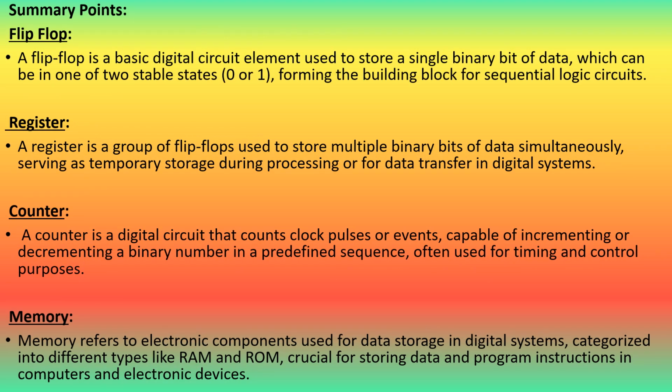Summary points. Flip-flop. A flip-flop is a basic digital circuit element used to store a single binary bit of data, which can be in one of two stable states, 0 or 1, forming the building block for sequential logic circuits. Register. A register is a group of flip-flops used to store multiple binary bits of data simultaneously, serving as temporary storage during processing or for data transfer in digital systems.